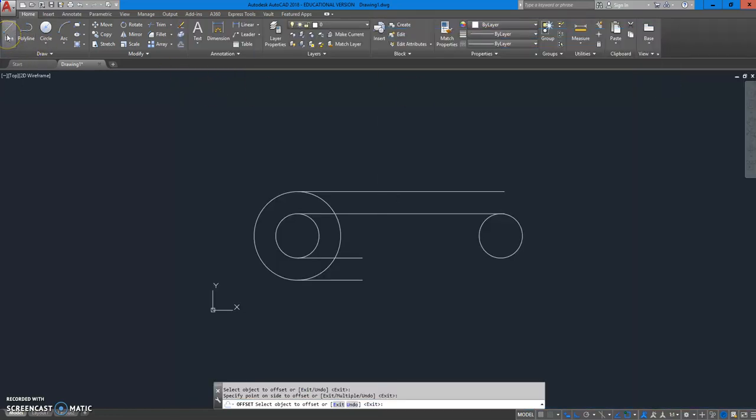So go up to your draw command, hit line, hit it again, hover over that end point until it actually shows up as a green square and you see end point. Come up. You know that that's a ½ inch. Close that boundary out. Come over, 0.5.